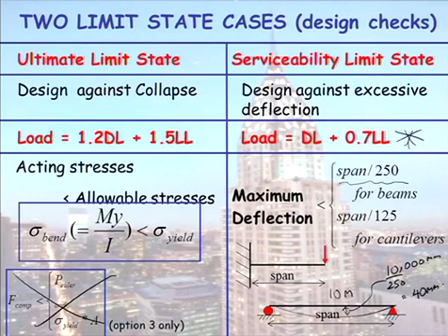So when your beam is 36 metres long, that means if you divide that 36, turn it into 36,000, divided by 250, that will tell you your beam can't deflect more than about 150 mil. When you then halve the span, your beam can't deflect more than about 70 mil. So I'll be showing you how to do that, to actually calculate the maximum deflection in 2 days. So there's something to look forward to.